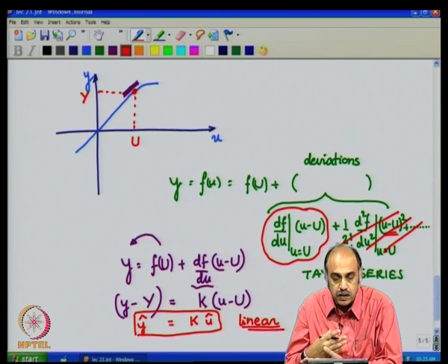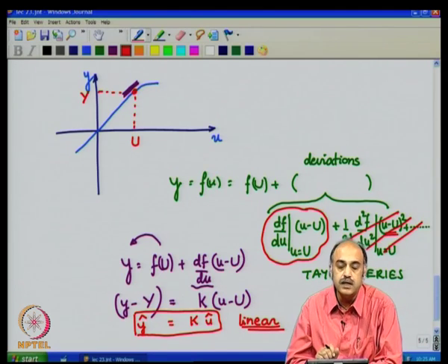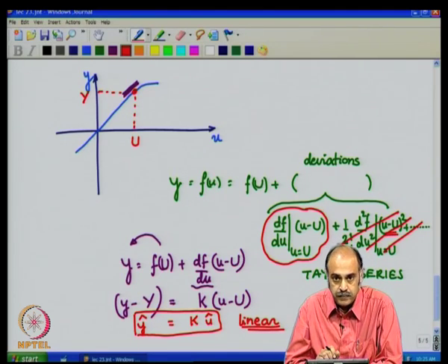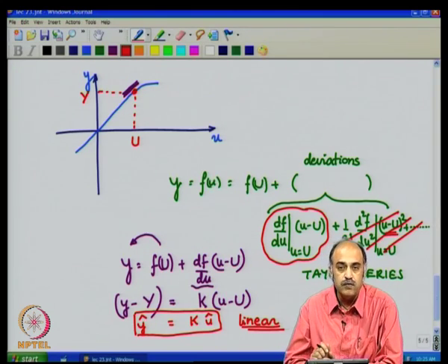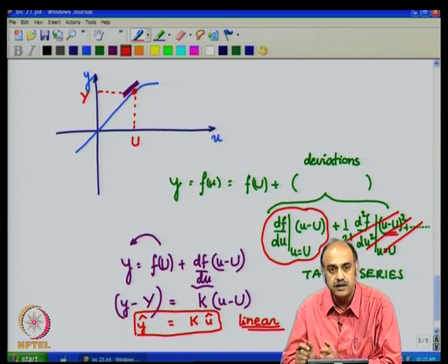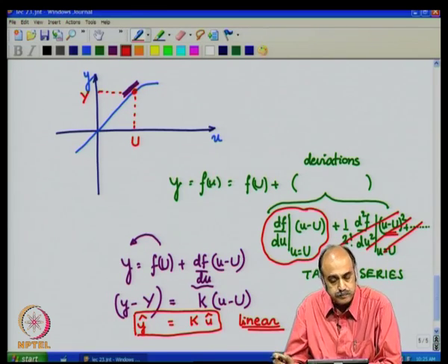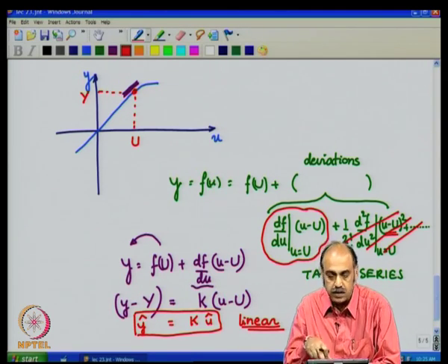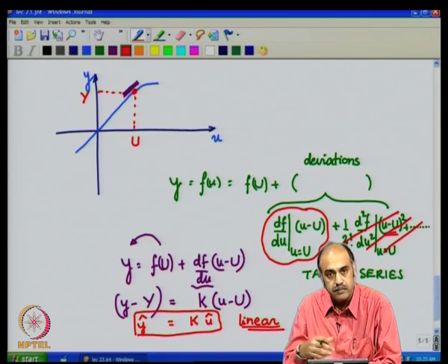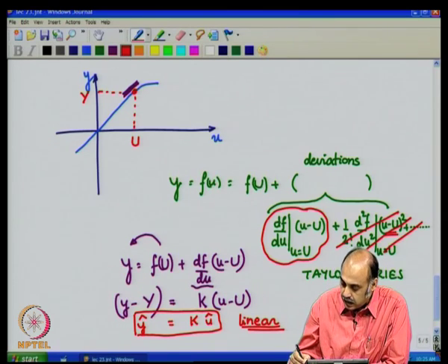And this is exactly what we have done in obtaining the small signal model state space representation of the DC-DC converter, where we obtained the average large signal model, and from the average large signal model we removed the steady state portion of the model. And when we were doing the average large signal model and multiplying the various variable terms which contain the uppercase and the lowercase hat terms, we neglected the small signal multiplication terms, assuming that they are insignificant, and therefore, we had only the first order terms, which made the whole system automatically linear. So, this is what you would arrive at.